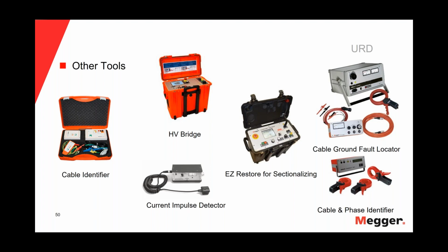And I call that arc reflection in a box. Basically, this is a tool where we've reduced the size and the weight down to an acceptable size so that a troubleman can have this tool always on his trouble truck so that he's ready to jump into power restoration using the arc reflection method.